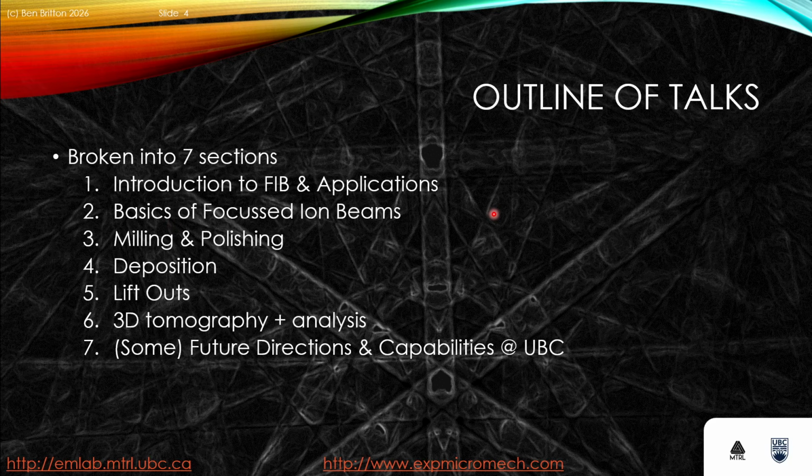We've got basics of focused ion beams, which gives us some underpinning theory behind ion-matter interactions and a few other details. Then we go into milling and polishing, which looks at how we mill and polish surfaces, an essential aspect of machining in particular parts. Then we've got deposition and etching using, say, gas injection systems to enhance our ability to protect surfaces, create 3-dimensional structures, and also remove material at faster rates.